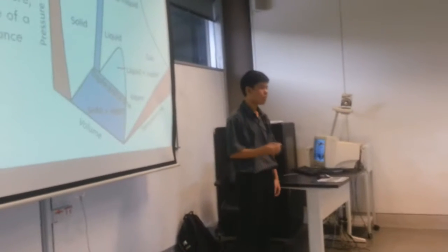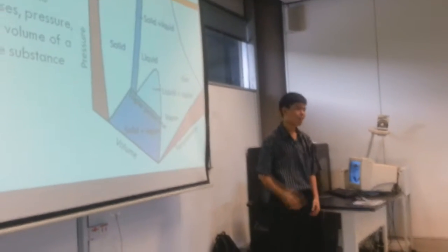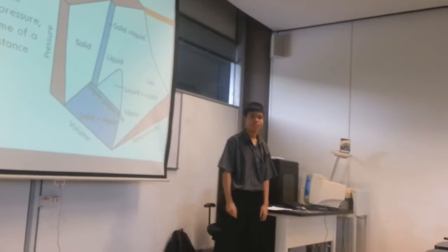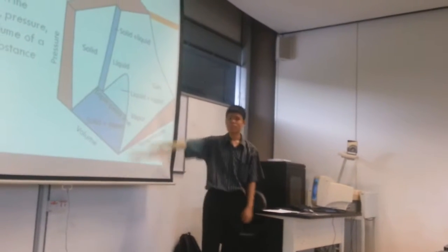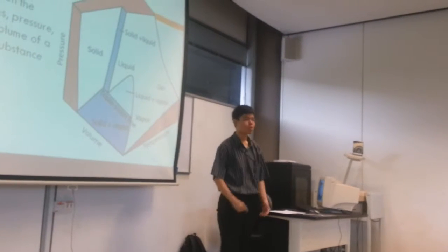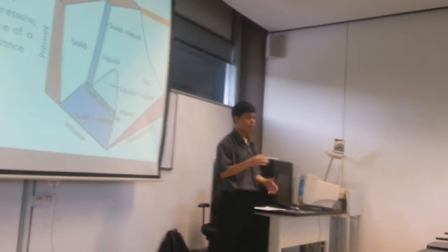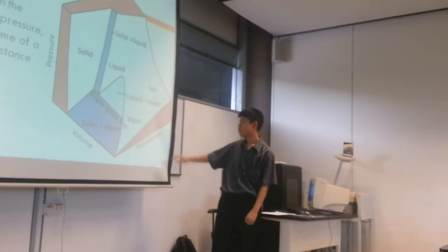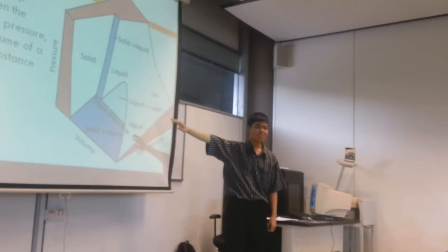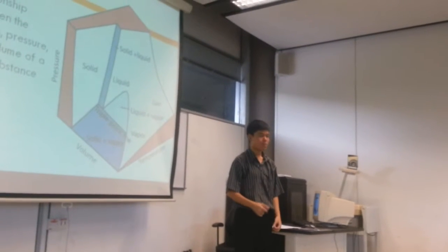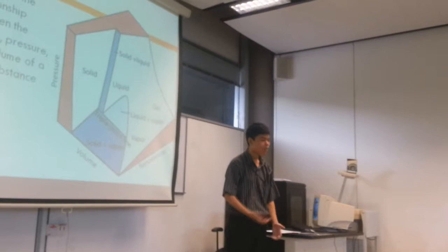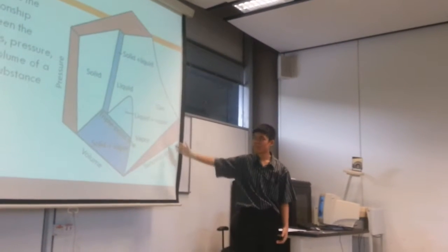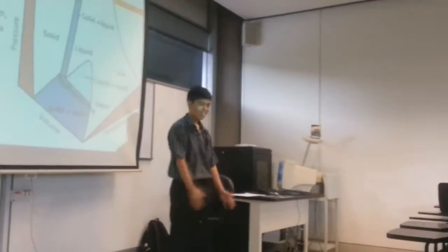And that's why you must listen in class, because this is very important. Not only does it relate to how all the unit operations are operated, it also concerns safety. For example, if you do not know that the pressure increases with temperature, you will not know that there's a pressure limit for every boiler and vessel in the industry. If you let the temperature increase too much, then the boiler will leak and possibly explode. So that's how serious this matter is. You must know thermodynamics in order to prevent this kind of accident. Thank you, students.